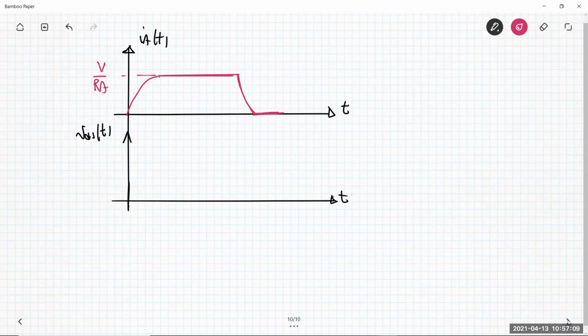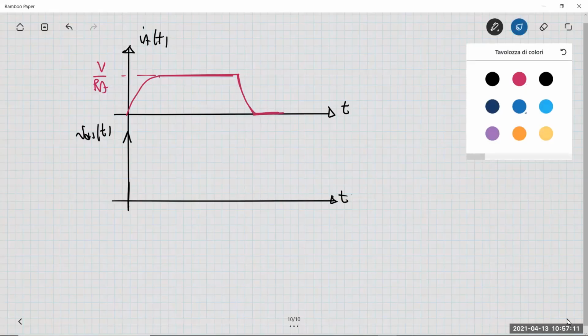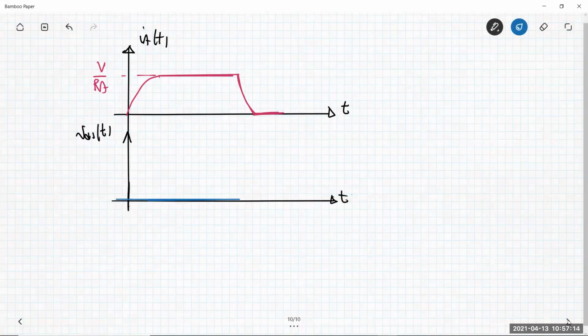The voltage VDS is something which is very close to zero when the MOSFET is on. And then what happens when you are turning off your MOSFET? You are no more going in the breakdown region. You just have, let's say, here something which is V plus VF, because here the diode is conducting, then you can go to V.